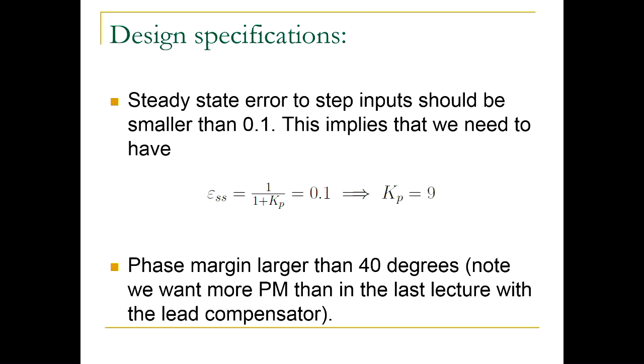Yep. And that K design, that's used in the final transfer function. So is your question, is this gain the only choice? Well, does that K design still remain in the transfer function? So in the end, the open loop transfer function for the compensated system would be G0 times C, right? And we are trying to figure out C, and we are always trying to design one thing at a time, right?